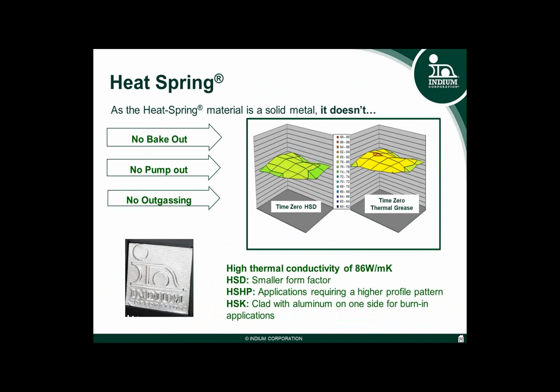You can see here, on the right-hand side, this is a thermal map. There are 16 thermocouples that have been measuring the temperature. If you imagine just looking at this, the green is a lower temperature, and like on the weather maps, when the sun is shining and you get into the hot zones, you're looking for red. In this case, a red zone is a hot zone and could be indicative of non-operation of your device as it gets too hot and maybe suffers thermal runaway.